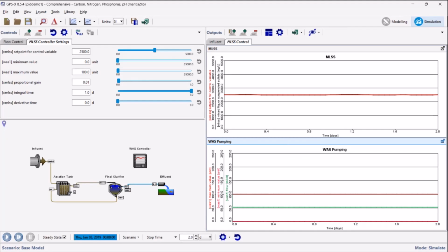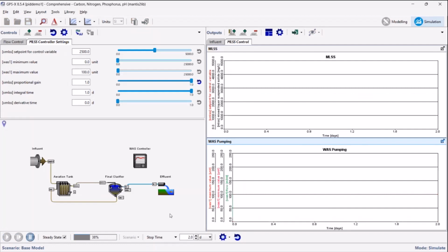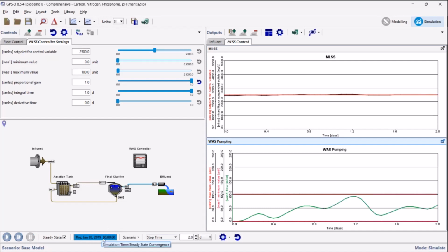Okay, so what happens if I make some changes here? I started this off in a good place, but I wanted to show you places where maybe it wouldn't behave quite that nicely. Right here, you can see there's some tuning that's gain. What if I had actually left the gain at the default of 1? So I'm going to rerun that. First of all, you can see down here that other issue I mentioned earlier: if you have over-aggressive controllers, it makes it harder to solve for steady state. In that case, it took 3 tries at getting it right before it got there.